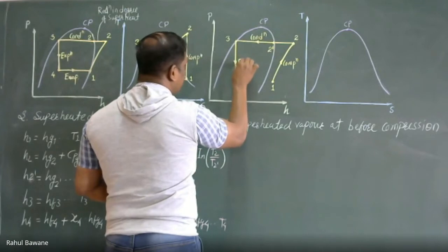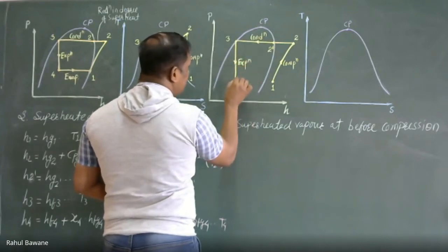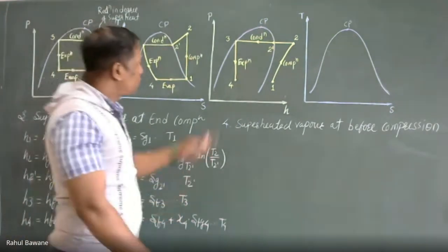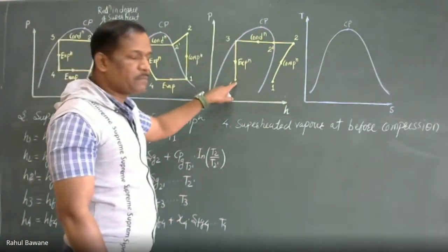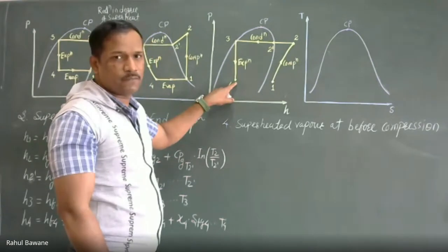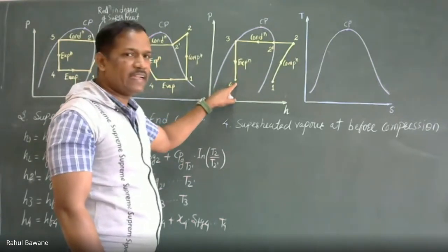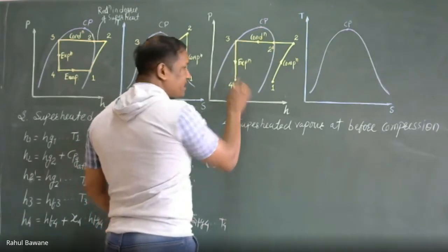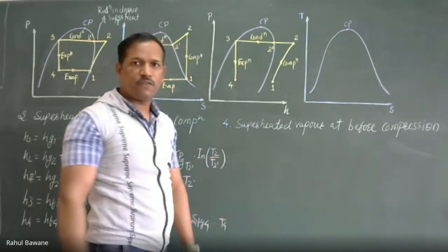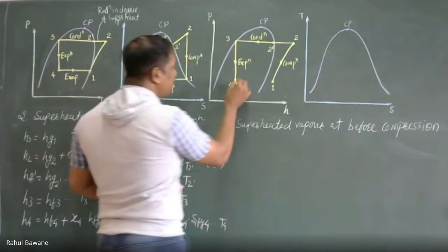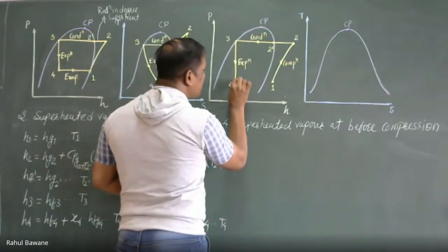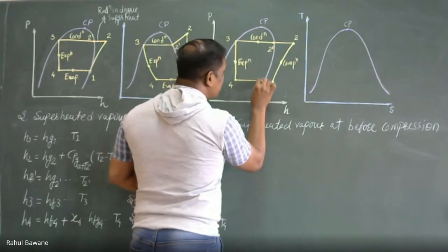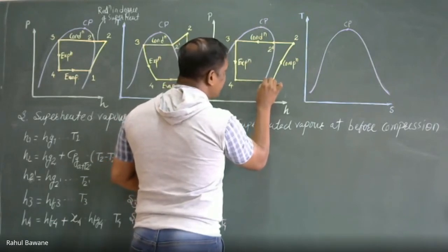This is expansion and it will reach 0.4. So after expansion, we observe our vapors become wet and this wet vapor enters into the evaporator. When it enters into the evaporator, it extracts latent heat from the food content and its dryness fraction will improve, so it becomes more dry, until it reaches the saturated dry condition.